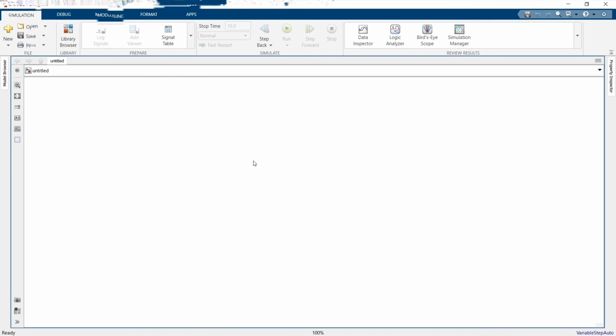I have to rotate it. Controller is done. Now, from where will I be getting the VBAT and IBAT? For that, I need to connect my current measurement and voltage measurement devices. This current measurement device I'll connect between my battery and the IGBT. This will measure the current. Then for voltage measurement, I'll connect this voltage measurement between the positive and negative ports. I'll just drag this current port to my IBAT and this voltage port to my VBAT.